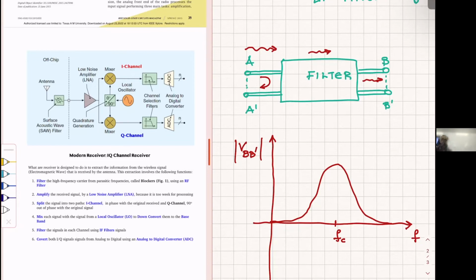And then what if your source comes this way? You're going to have a filter the way we do them. They're not active filters. These are passive filters. They're linear devices, and most of them will be symmetric, so you will see the same thing. But in reality, if you have 2 ports, and for each port you have 2 coefficients to characterize, then you need 4 coefficients to characterize a 2-port network. So we call that a network, and the coefficients we need to characterize it we call scattering parameters. So we'll go to network theory to be able to talk about this carefully.